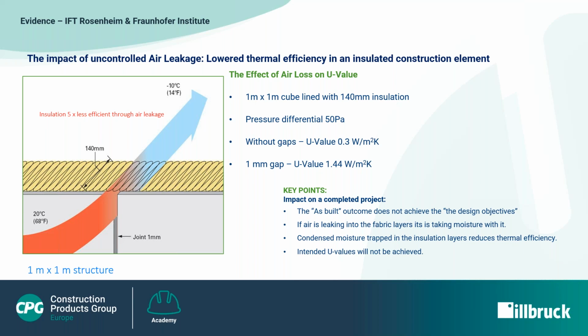The Glaser method assumes a static state through the centre of a layer set of wall components over a period of time, e.g. the seasons, and a range of average recorded seasonal temperatures for a generic set of UK geographical regions. Whilst helpful, the Glaser method cannot take into account liquid water or water vapour transport, nor can it take into account air leakage.